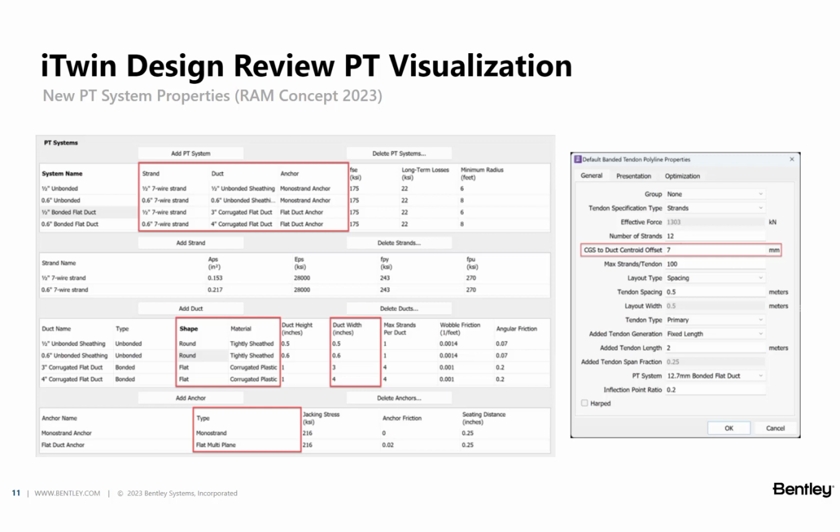So RAM Concept users can utilize these properties to visualize the geometry of both the duct and the tendon strands that the duct contains, and then better verify the duct cover requirements using the iTwin Design Review workflow.